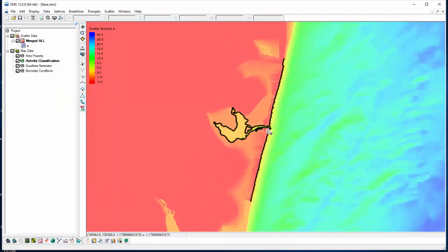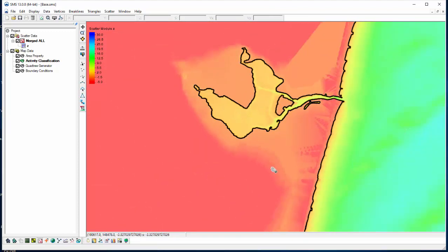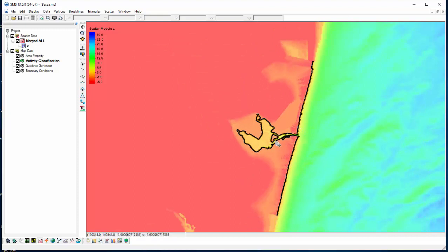We're still approximately at the same step, so I can move on for this webinar. So we've cleaned this up. We've got one arc for this entire area, but we don't have any polygons. And so polygons are basically created by arcs that close on themselves. And so we see this coastline is not closed. We need to do that.